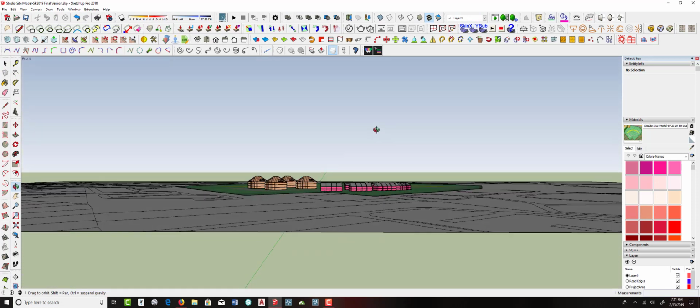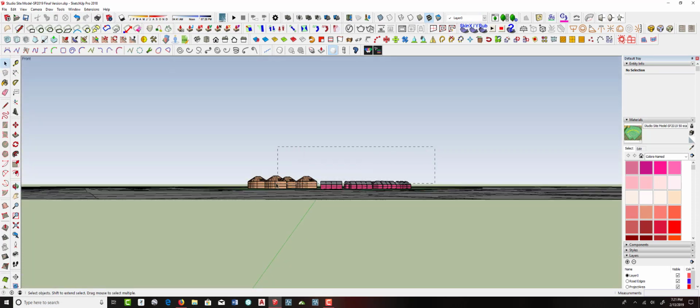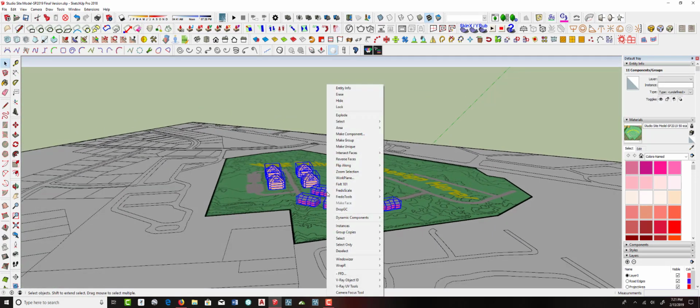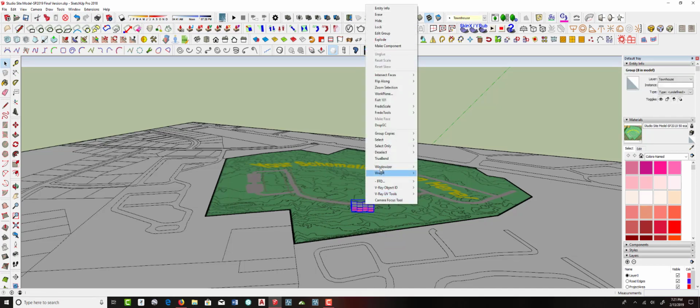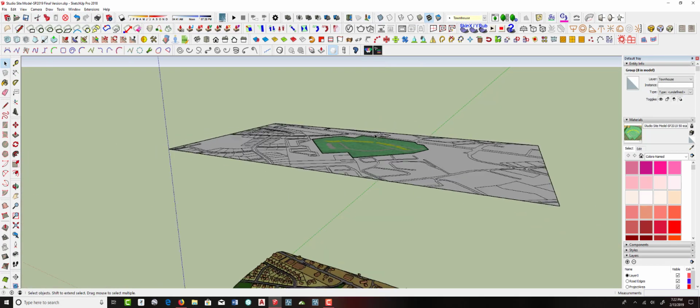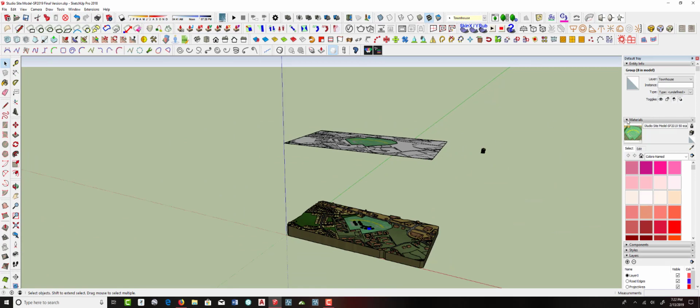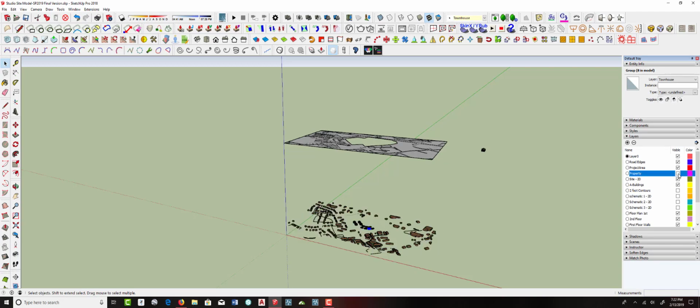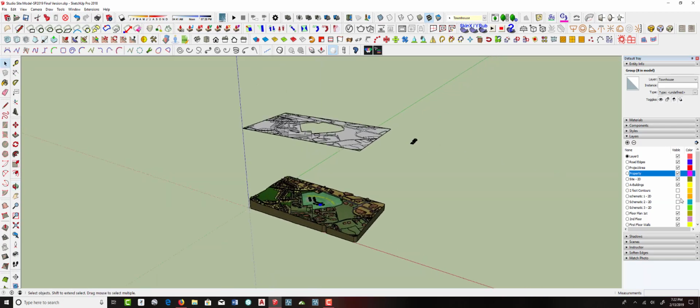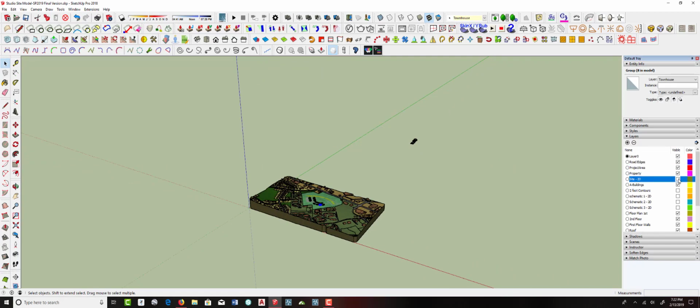So what I really want to do is get these down on the terrain model. So I'm just going to select across the tops, make sure I just have those. Right-click, choose the Drop GC plugin. And if it doesn't work, you can grab that one, try it again, Drop GC. There we go. Now, just to make things a little easier to work with, I'm going to get rid of that version, property, not that one. Let's see, what layer is that on? Site 2D, there we go.